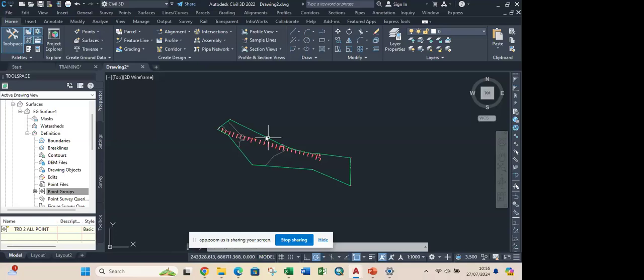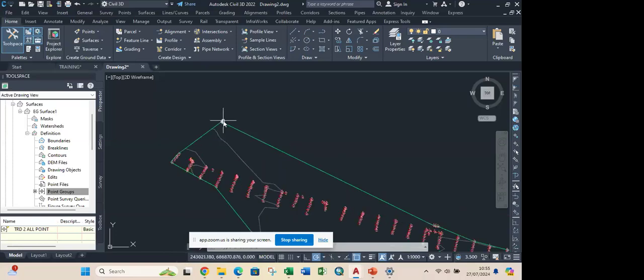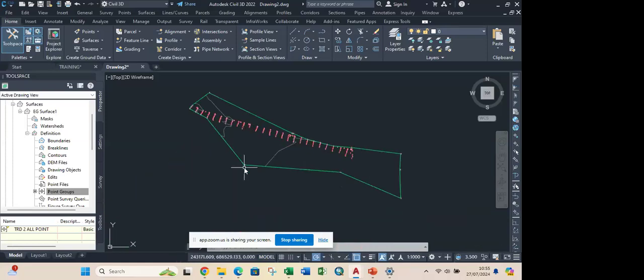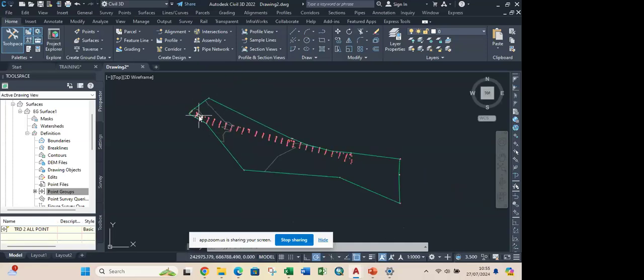Along the entire area the surveyor covered. So you can see these extensions now. These ones are seen here. These are the TBM locations, temporary benchmark establishment sites. So this now is the surface created for a particular project. If I'm working now, any work I'm doing outside the surface shows that there's no data captured on this whole area. So my work will be restricted inside the surface.